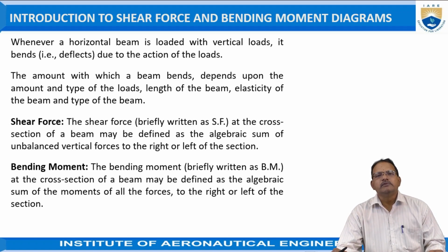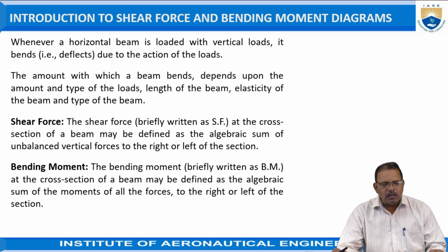The vertical loads which are acting on the beam are generally considered as shear forces. Here the word shear force represents the unbalanced vertical force which is acting on the beam, considering with respect to the point toward the right side or left side of the section.